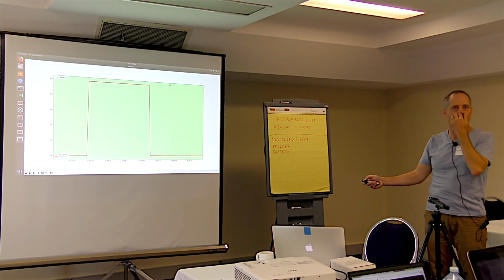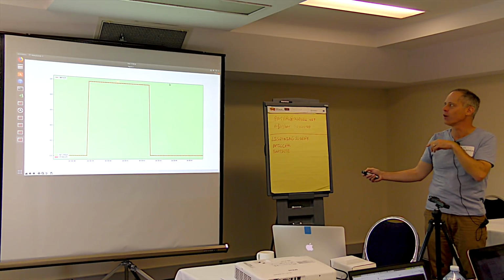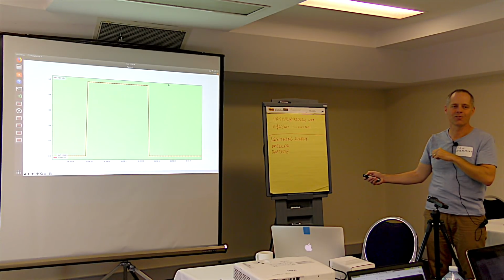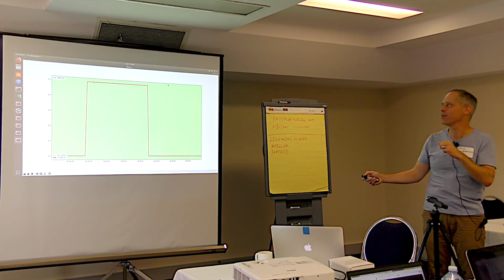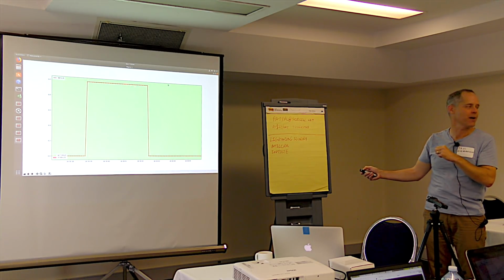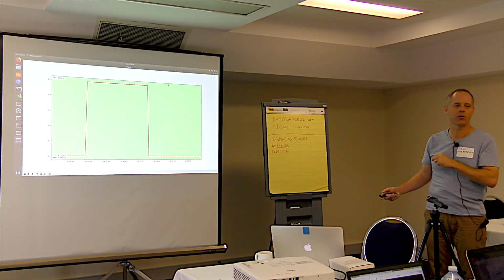I don't think that was the one that he was using. That was obviously not rotated because it continued to fly. That instance, this is what got me a bit confused looking at the log, just as it took off. Just as it took off, yeah. Now it's flying on that EKF, and at some point in time that gets unhappy because of the magnetometer errors. And then it switched to the first instance, and then it rolled upside down.